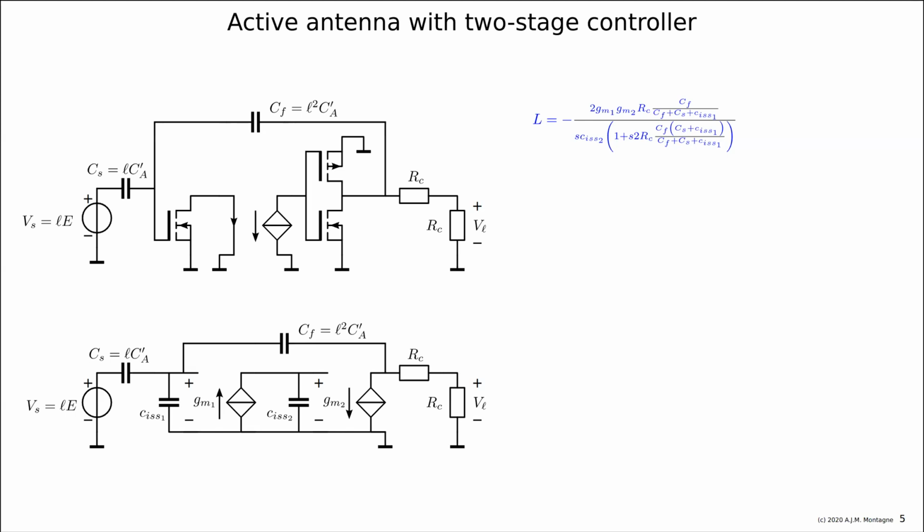So this is how I write down such an expression. I'm not going to network theory and do all these substitutions and write 5 pages. I just do it in this simple and short way. Now, for the bandwidth estimation, we need to have the product of the loop gain and the poles, the so-called loop gain poles product. So the only thing I need to do is remove the 1 and the s's from this expression, and then I have the loop gain poles product, and then you can simplify this expression as is shown here.